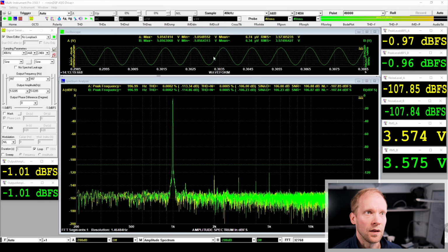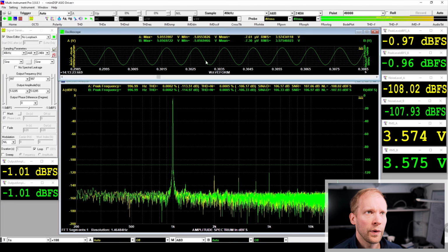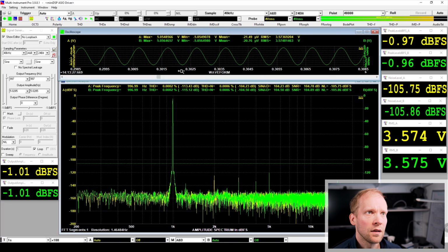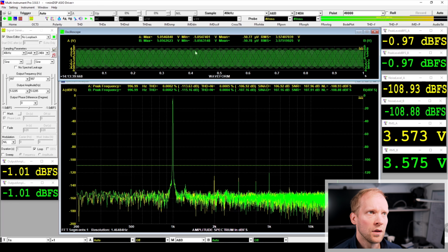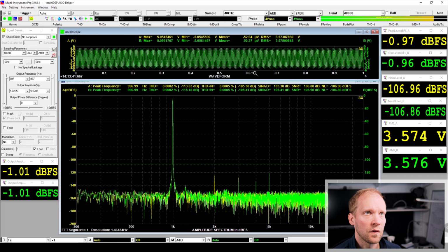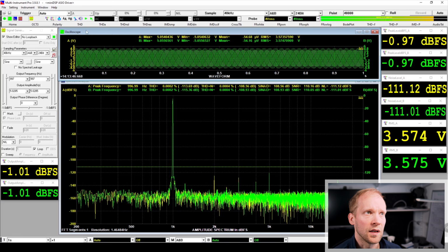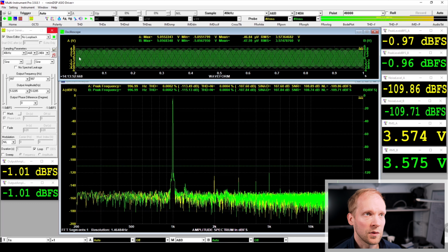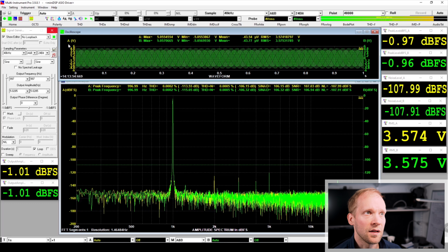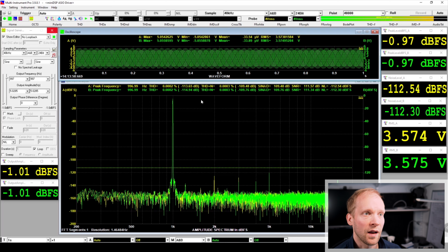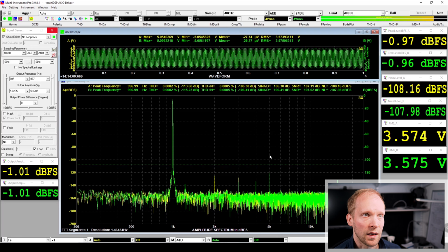How do we get this FFT then? We have this time domain representation here. Let's just zoom out. So this is the capture the software is taking. It's around 1 second of this signal. It captures this block of signal, and then it does the fast Fourier transform calculation and creates this plot here.